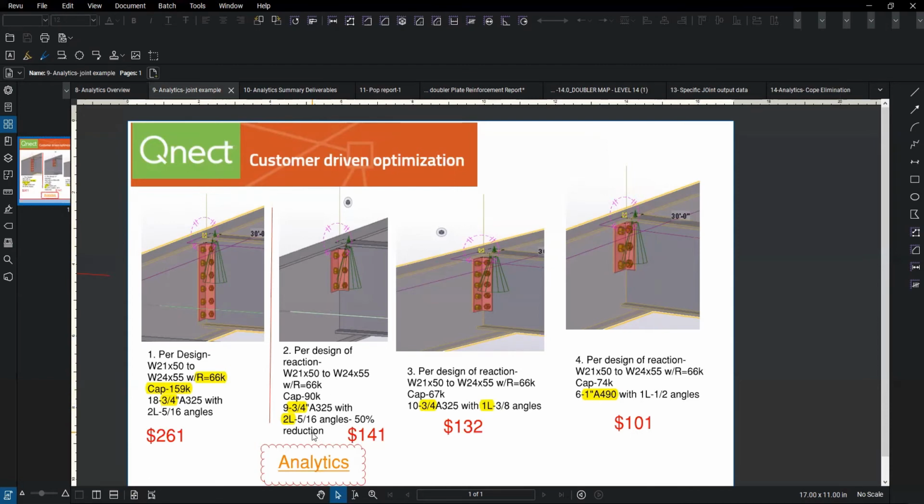Again, we're talking about jobs where we have the opportunity to design. If this was a mandated job, we would simply mimic the connections, capture the data, move it to the EPM process. So moving on to this example, so we now have a connection that's half this one, and at this point, as a bidder, you're not going to reduce your price because you don't have permission, but you could condition your bid because you can reduce the number of bolts in the connection. So you can condition your bid for a lower cost, lower schedule, or both, pending acceptance of the elimination of this fill the beam up.